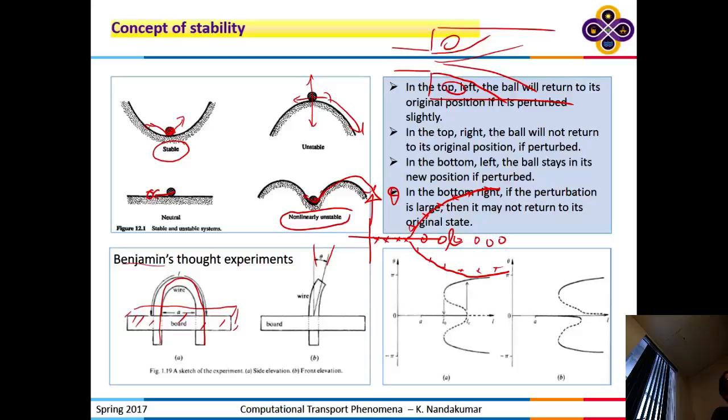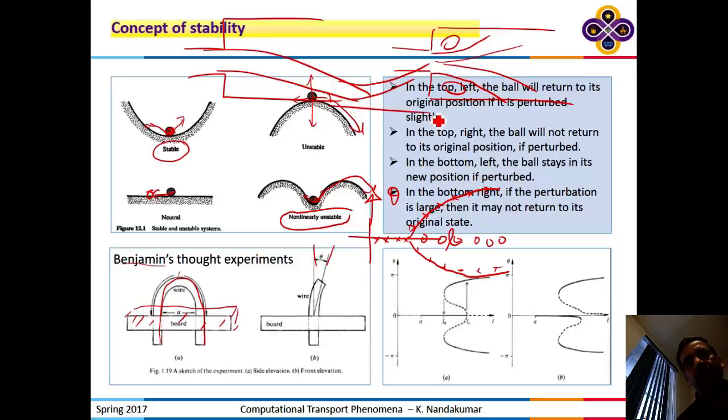It's very easy to set up in COMSOL. Okay? But what you will find is, as you increase the flow rate, the symmetry is broken. And then you have a jet that would go something like this. One of the vortices becomes small, the other one becomes large. The jet preferentially goes over one side, and it is steady state. But if you take the mirror image of that, that will also be a solution. So you can trigger the solution to go into the other state as well.